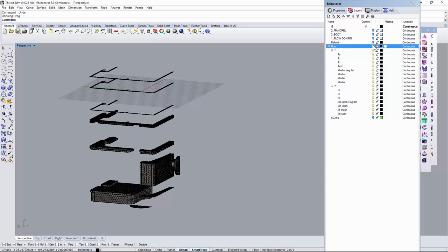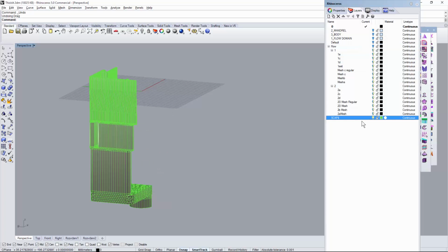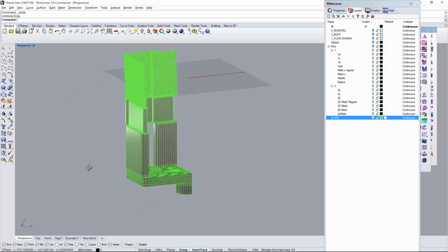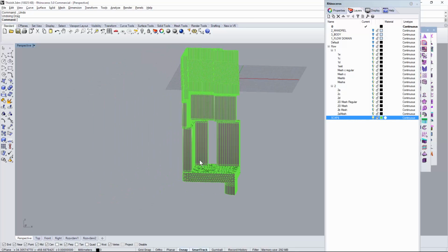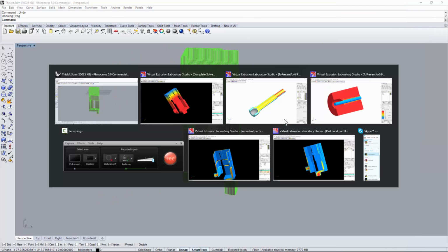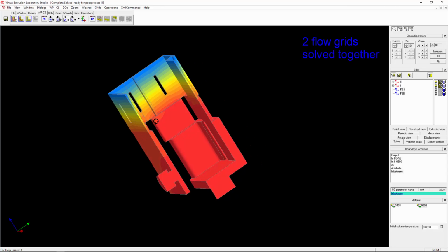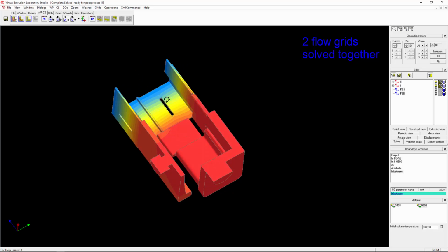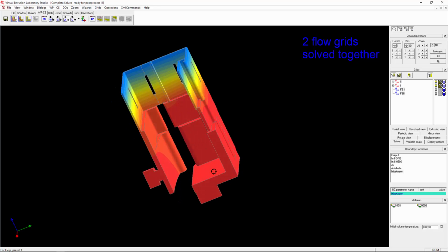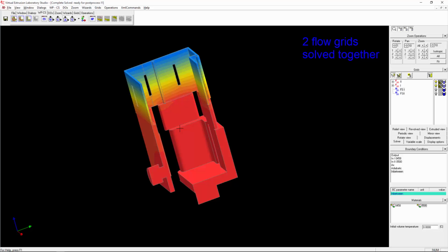And then at the end, when we do it, we just end up with the complete long elements here, and then we can bring them to our program. The advantage is that we save a lot of elements here, and we have a very good quality mesh with lots of elements across, and also these sections here are very straight.